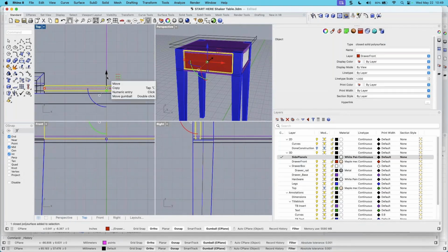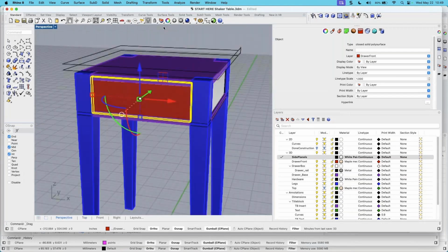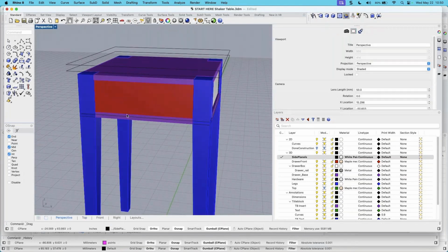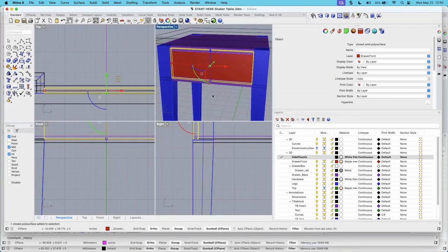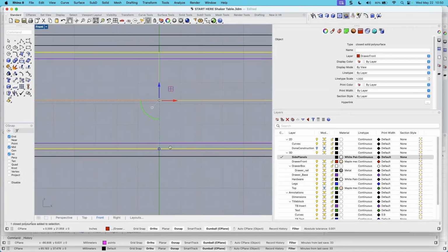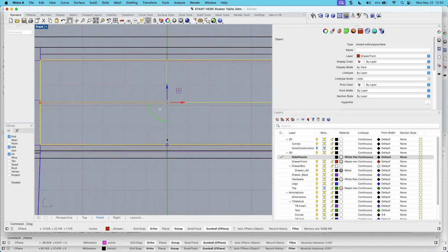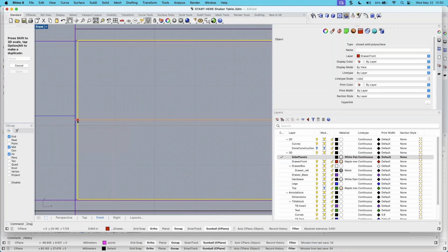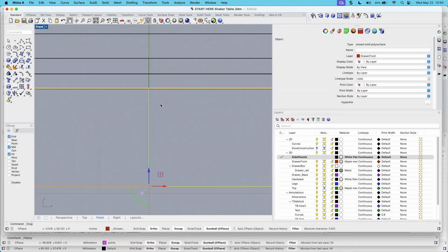Okay, so it's going to fit inside that space, and you could scale it from the centroid, or you can just visually scale it until it stops intersecting the front base. I like to scale from the front view, and in this case, using the gumball, it becomes a really great way to visualize where the edges of the cabinet are, in this case, the leg, and then in this case, the top and the bottom.